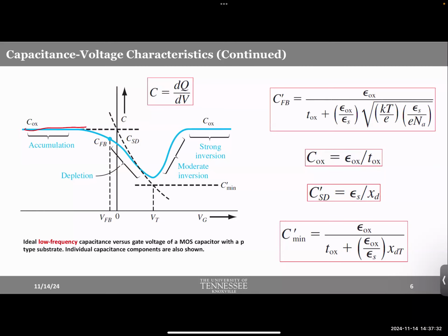Just by looking at the CV property, you could understand where the threshold voltage of the MOSFET is. Isn't that interesting? Remember all those discussions we had in the previous lecture about how to calculate threshold voltage? This is the equation, metal semiconductor work function difference, all those good stuff. Well, nobody does math in actual real life. They do experiments. Now, they used to do math.